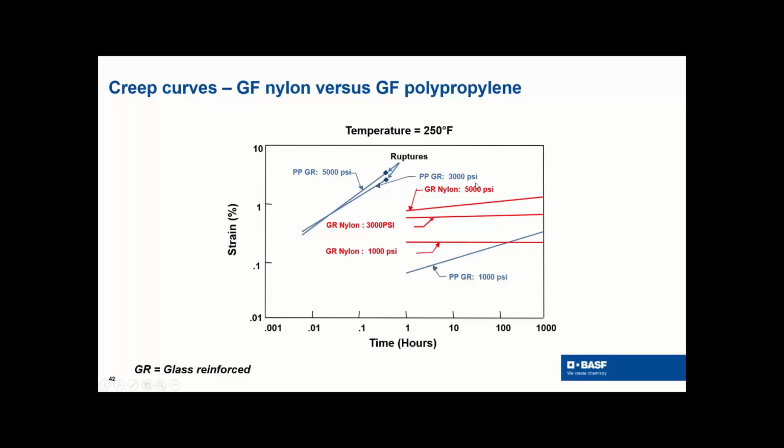In this case, a nylon. If you had 5,000 in your original design, again, you have that little bit of slope. It's probably going to last well above 1,000, maybe 10,000, maybe even 100,000. That might be acceptable, but a better design is probably going to 3,000, and here it's probably going to last a lifetime. And then if you're really conservative, you can go down to 1,000, but this will last 2 lifetimes.